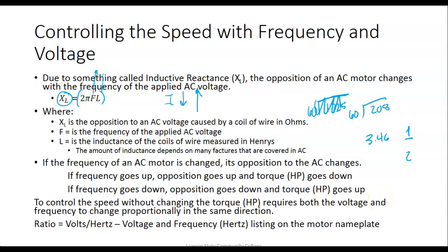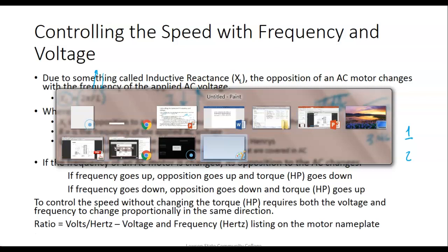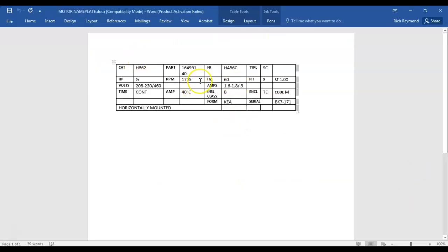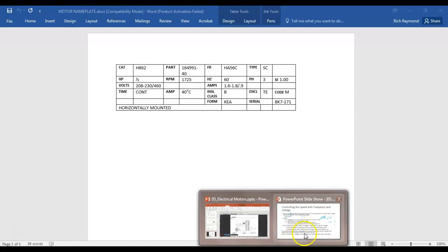Basically, the way you program a variable speed AC drive, you just enter this information right off the nameplate. They called it, so it's got a bad name, a variable frequency drive. But if you just change the frequency, you'll either burn the motor up or you'd stall it when you try to change the speed. So they're changing what? They're changing the voltage and the frequency together to cause the thing to run. So I like to call them variable speed drives, but everybody corrects me: so, you mean a variable frequency drive? And that's what they're called in the industry.